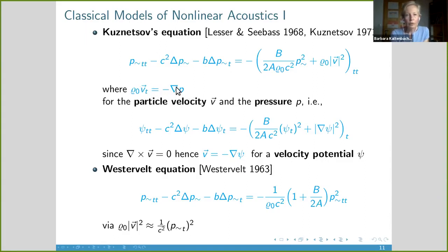And so we also have to take into account this relation between velocity and pressure, which is actually the linearized balance of momentum equation. Also notice that these quadratic nonlinearities are under a second time derivative. So it's relatively high order nonlinearities that we have to deal with here.